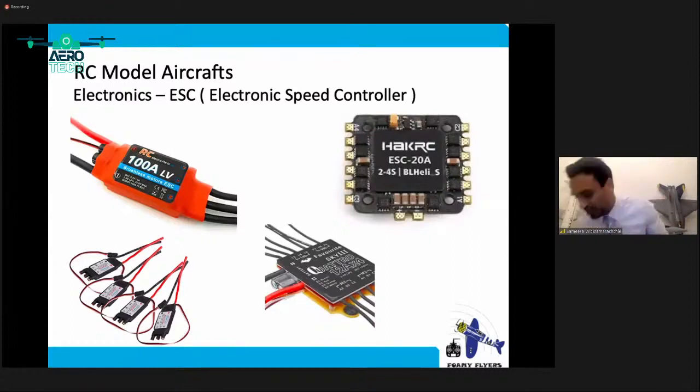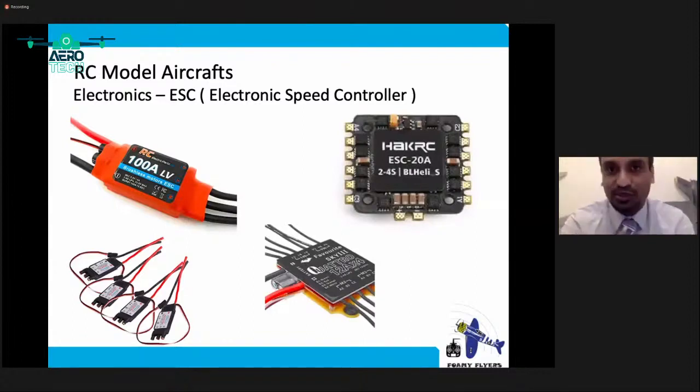And the other thing is, we've talked about this being for electric motor driven aircraft, but if you're not having an electric motor driven aircraft, let's say you are flying a nitro aircraft, then obviously you need something to power the electronics. There's something called a UBEC where you can get this as well. Basically it does the same thing. You get power from a battery and distribute it without any interruptions throughout the electronics that you have on your particular aircraft.